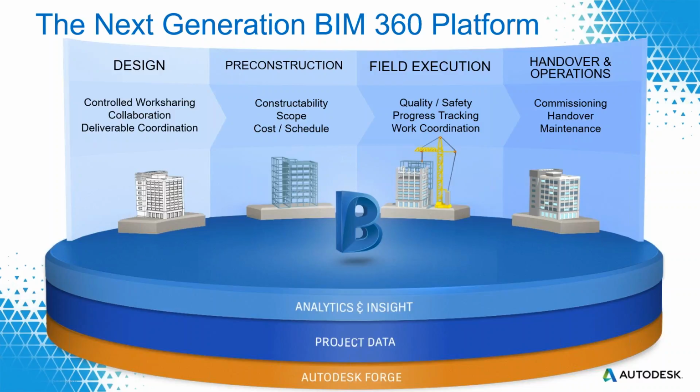So your design teams can begin doing their work using a tool like BIM 360 Design. And as they go through, that information can be brought up to a coordination level using BIM 360 Glue. We can then take that out for field execution, leveraging BIM 360 Layout and other tools to help us manage the models and bring that value out into the field.